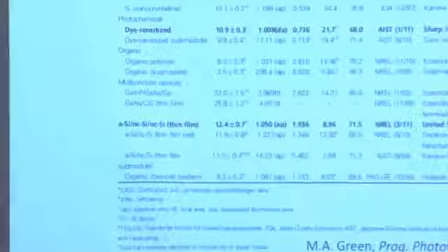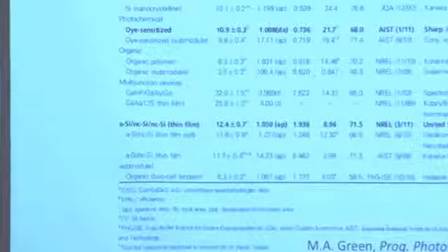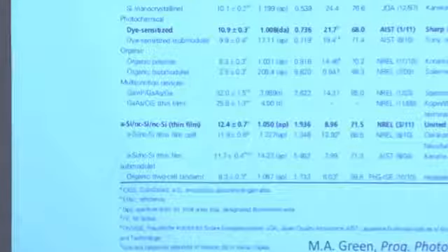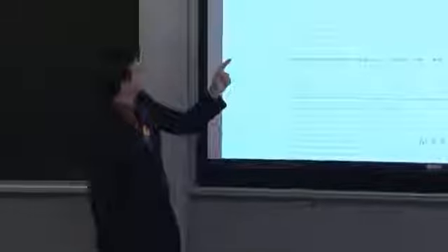Is anybody surprised at that number? Ashley, did you expect it to be that big? No, not that big. Not that big, right? Yeah. But say the record efficiency crystalline silicon device, 25%, plus or minus 0.5. It's a pretty large delta. We'll explain some of the reasons why that error bar is so large. Another thing to keep in mind, look at gallium arsenide at 28.1%, just achieved by Alta Devices in March. Keep that number, 28.1 plus or minus 0.8%, in your mind, at least the first one, 28.1.